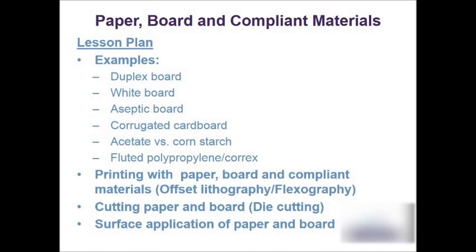Okay, so the fourth type of paperboard and card I'm going to speak to you about is whiteboard. Now, whiteboard is a very high spec type of card. It is the most expensive card per grams per square metre. That's because it is a high quality finish card. You most often see whiteboard in greetings cards. The greetings cards normally have a shiny outside and a shiny inside. That means that they've been treated to a high level and quite occasionally are also laminated.